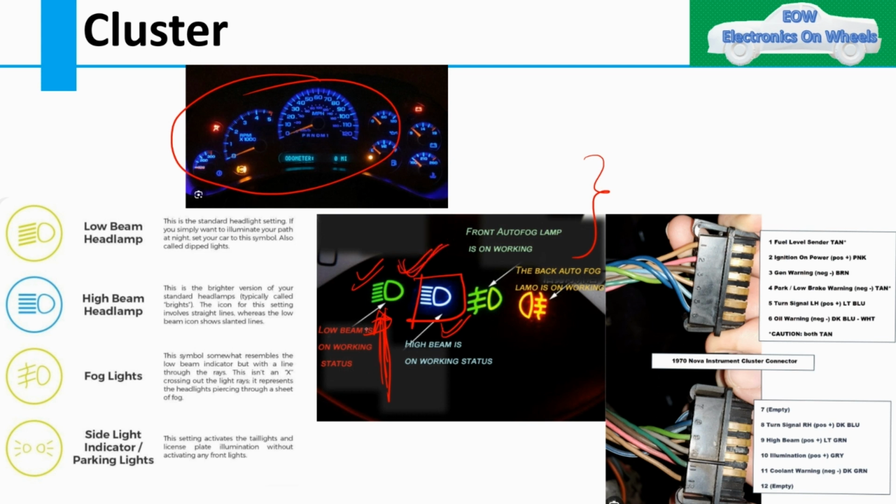Can we take the low beam telltale in the cluster or not? We can discuss this point in detail, and the logic behind it. But as of now, understand that only the high beam telltale will be in your cluster. When you switch on the high beam, this telltale will come in your cluster and tell the driver that you have switched on your high beam.